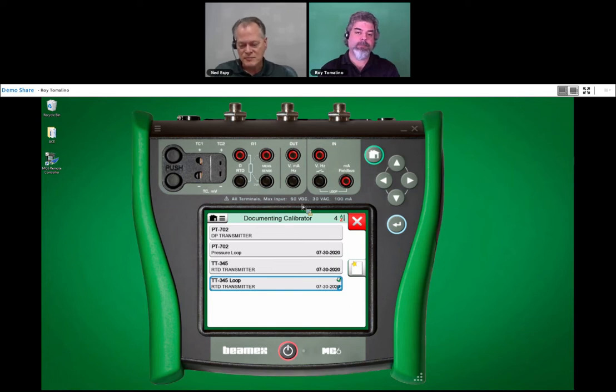So you can sit there and do that test by yourself. But if you'd have pulled the probe and done a 3-point check, that might have taken 15 minutes just to run the dry block, plus the time to pull it out of the process, and then some more minutes to put it back in service.